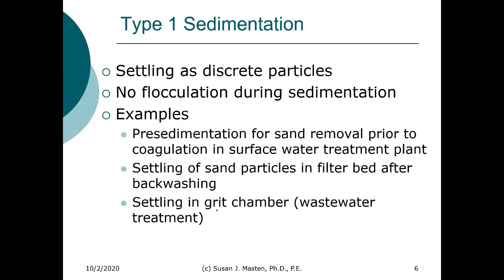So if you think about mixing sand and water and allowing that sand to settle, the sand just settles and it's not interacting with another particle. There's no particle growth during sedimentation. This can occur if you have pre-sedimentation for sand removal in a surface water treatment. I didn't draw that, but you could have pre-sedimentation before you even do the rapid mixing.